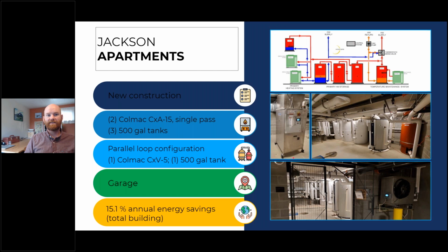But due to the sizing of it, we had to re-evaluate what temperature maintenance heat pump we were utilizing. And this temperature maintenance heat pump, manufactured by Colmac, has a fan on a hinged face. And so we didn't want to worry about the ducting connecting to that fan with hinges for access internal to get into that unit.